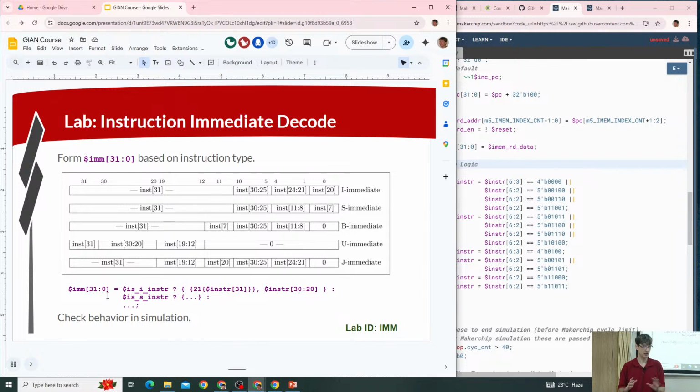Obviously the instruction itself has fewer than 32 bits. We're feeding into some operation that's going to be a 32-bit operation, whether that's the arithmetic logic unit, where it's providing an operand, and the arithmetic logic unit is designed to operate on 32-bit values because it might be operating on register values, or the immediate, or whether the immediate is an offset for a branch, it's going to be added to a 32-bit value.